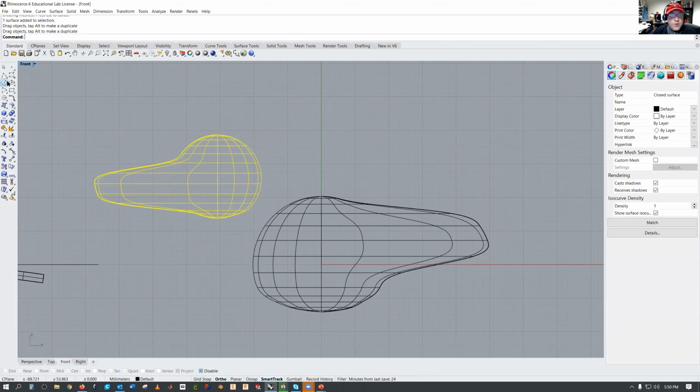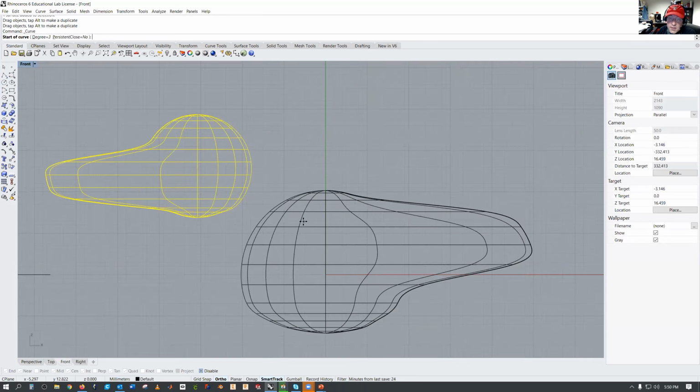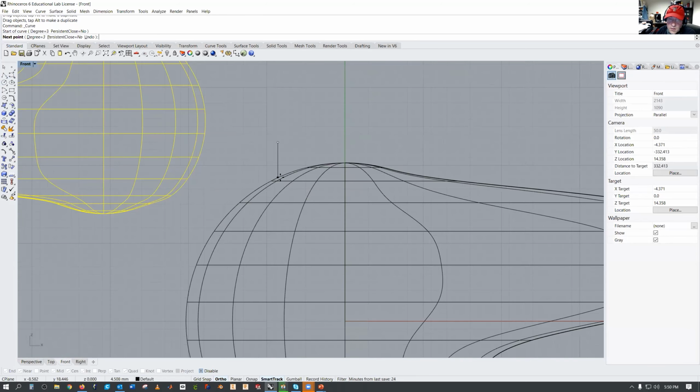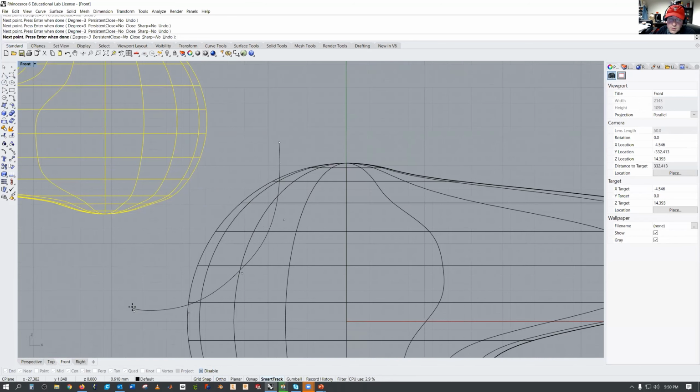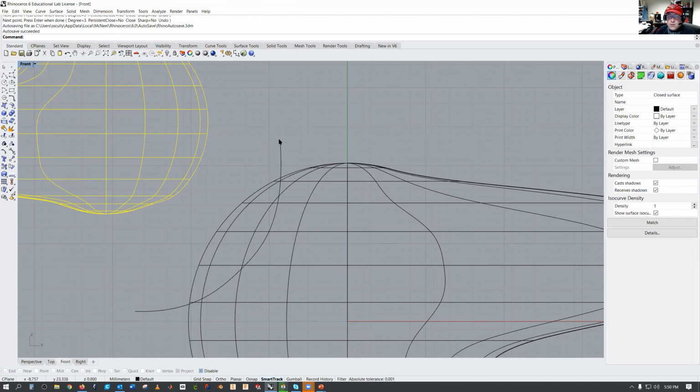So what we'll do is we'll create a line, a control point curve. So just like these spheres are defined by control point curves, we'll make a curve of our own instead of a straight line curve or a polyline. Here I'm going to turn off ortho, and then I have a little bit more control. And what you want to do, hit enter, is start outside your object, move into your object, and then end outside of your object.